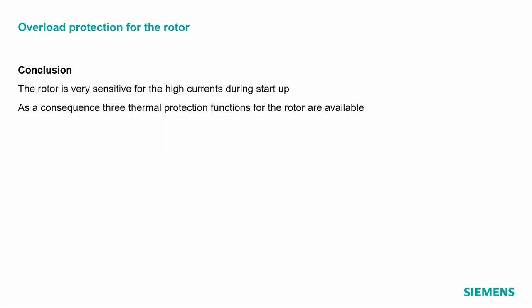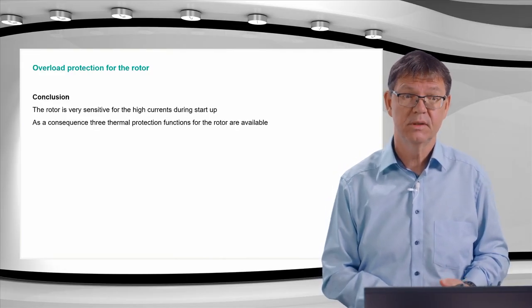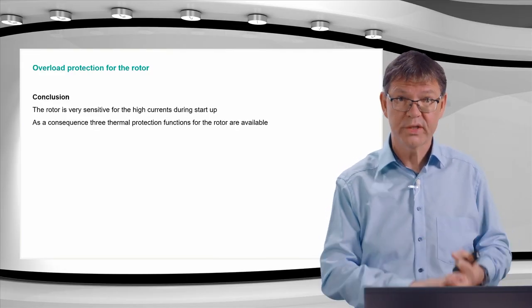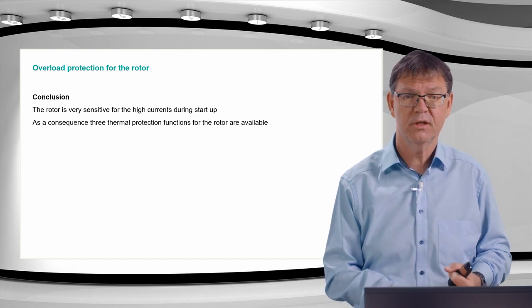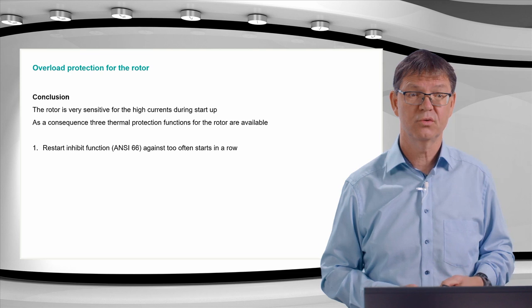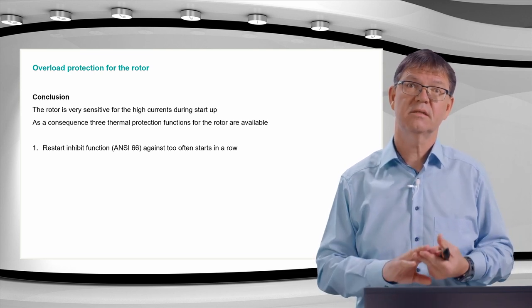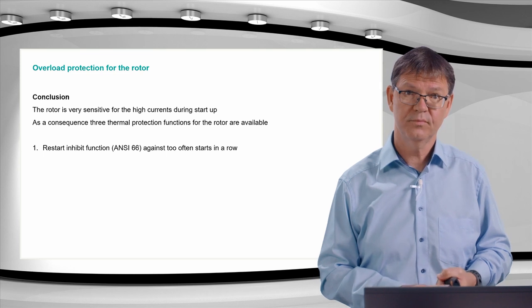Conclusion. The rotor is very sensitive to high currents during startup, and we have more than one function, three thermal protection functions for the rotor, depending on the task or purpose. The first one is the restart inhibit function, which protects against starting too often in a row.